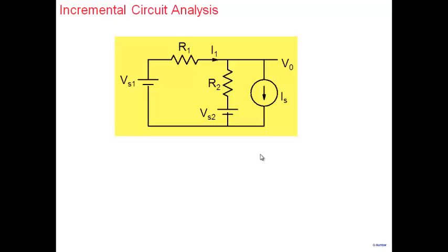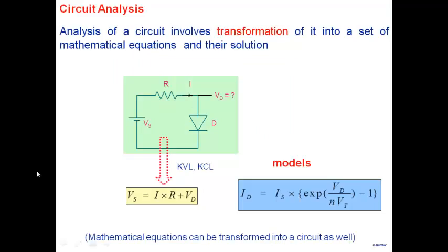Although we remember the model, for example, your 0.7 volt model of the diode, we know that we are approximating the diode by 0.7 volt. What if I apply a voltage here which is 0.6? What would happen? You replace the diode by a 0.7 volt battery, and I apply a voltage of 0.6, it would appear as if the diode is the source of current.